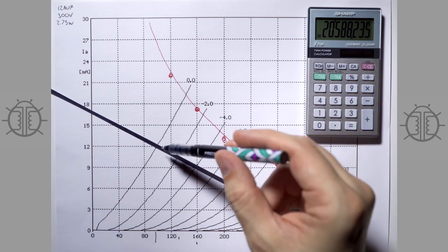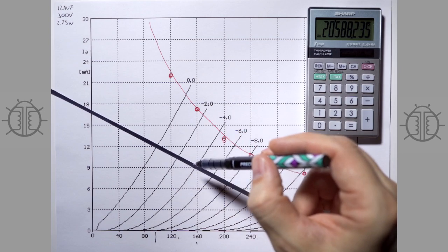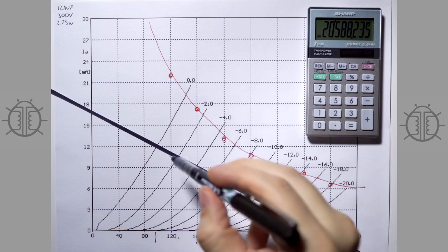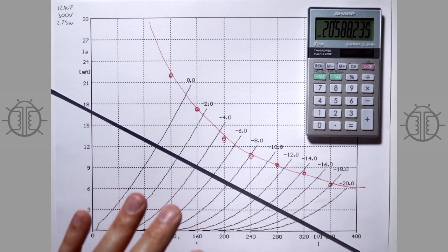You can see that the voltage difference between here and here is pretty similar to here and here. However, if your next stage, for instance, is a power output tube, and it needs something like 100 volts or something, peak to clip, then you're stuck trying to get more swing out of your tube, and so you're into a less linear zone.